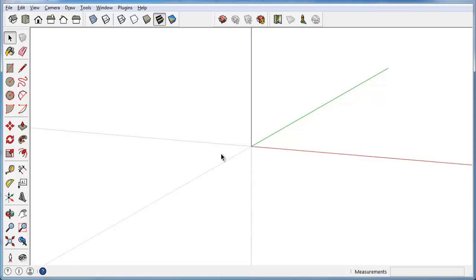As you can see here, we do have a blank canvas, and this is something that if you want to, you can start here. You don't have to start with any kind of data, but more than likely, and you can confirm this, Ian, you will probably have some kind of asset to work with as a base to model from. Yeah, a lot of times when you're going after a project, you'll start out with some PDF documentation or even just paperwork that you can scan in, and we're going to walk through that process of converting that into an image and bringing it into SketchUp as a background. Yep. So yeah, let me go ahead and do that.